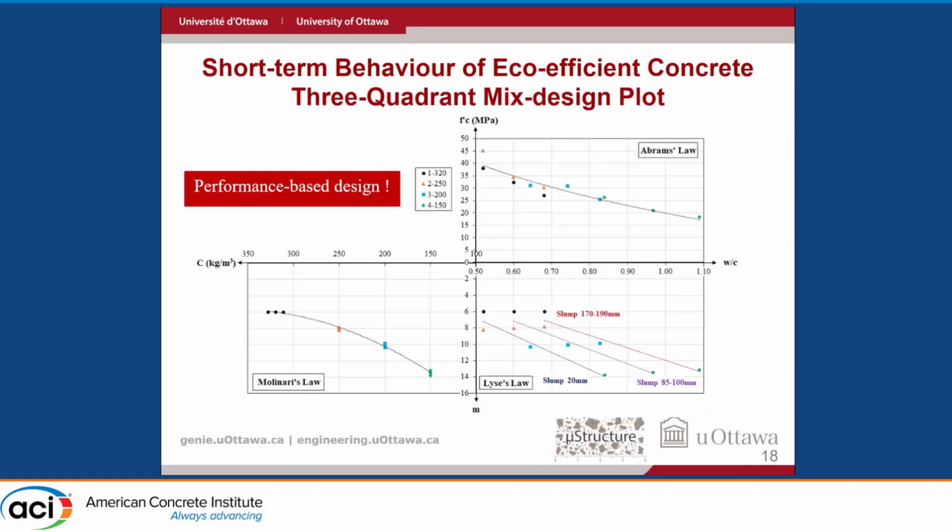So with all of those things, what we proposed, and that was amongst the endpoints of my PhD, is to have a performance-based approach, which is not necessarily related only to the descriptive methods, where we need a water-cement ratio, we need this or we need that, but are we getting performance out of those water-cement ratios that are required? So I believe that we need something that is more dependent on performance. And then, of course, we can discuss which type of performance we need for different mixes.